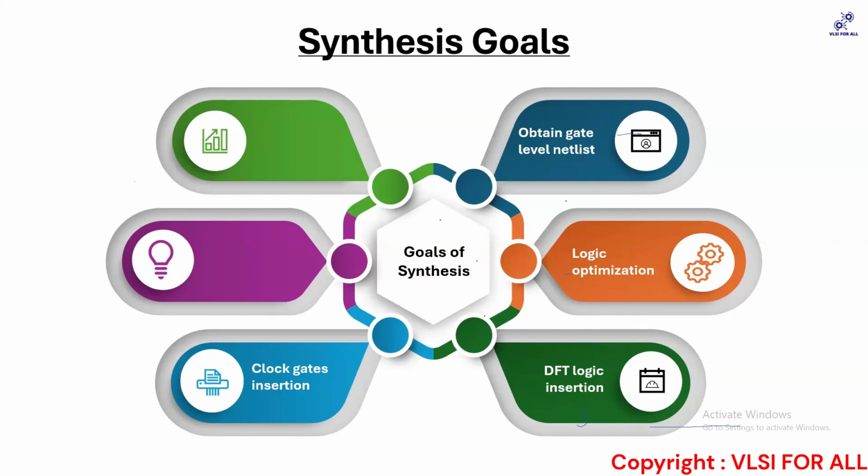Okay, ma'am. What I'm thinking is, if it's done in synthesis, then we can save time during PNR. Yeah, but I'm saying that for placement, there is no sure guarantee that whatever placement you have will hold. See, you can also dump a def and give it to them. Okay, there is an industry standard that the synthesis team can give us a def. But for example, the person who did an analysis may say, I don't want to go with this def. I have the netlist. Let me try my own placement, right?